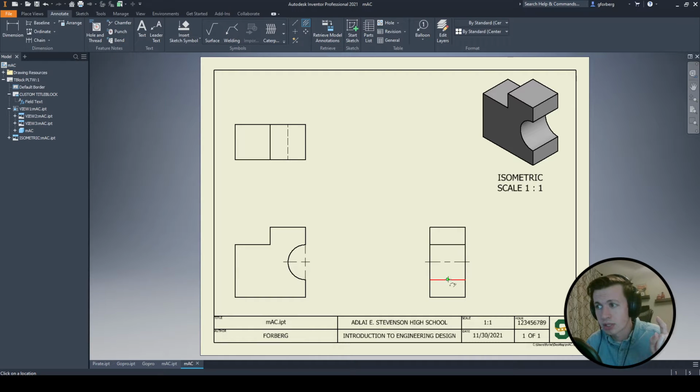So I click on this line and this line, and I add my center line through over there. On here, we have the line precedent rule happening, so we've got a solid visible line. And yes, if you really wanted to argue, you could grab a centerline tool and throw that right there just to illustrate. Grab the centerline tool, go from corner to corner, right click and hit create. And now we just have those little marks that show that there's a center point going through there, but it really is hard to tell.